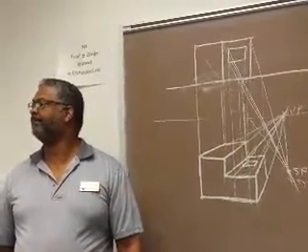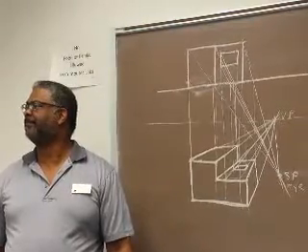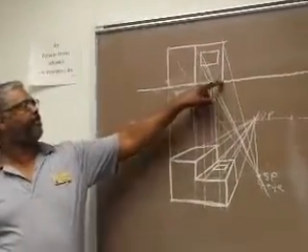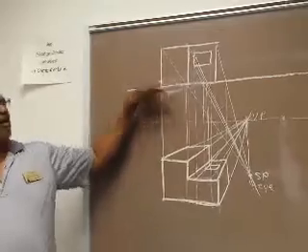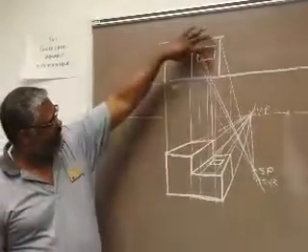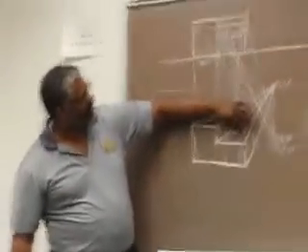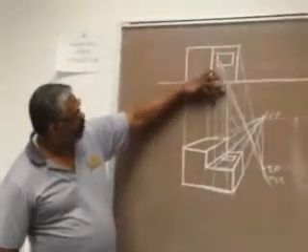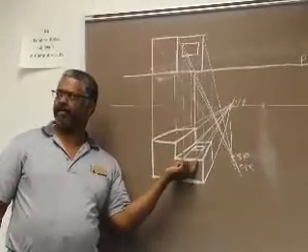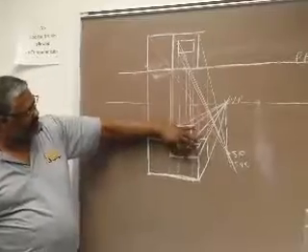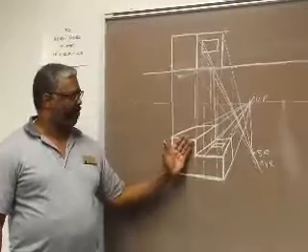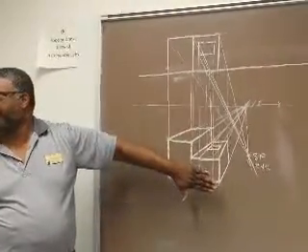The front view in perspective is not going to match the straight-on view that we have on the sheet. Well, the part that sits on the picture plane will match perfectly. Anything off of that won't match up, but if I'm trying to determine the size of this, I at least have to draw a reference line straight down so that I know in this view it's this big. And then as it goes back it gets smaller and smaller. So that's why initially the features should be on your front plane for true size.